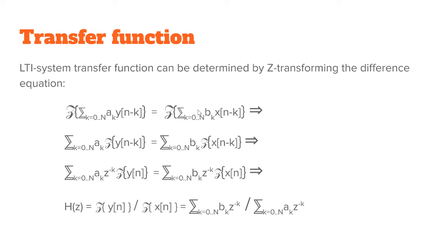So the transfer function for any linear time invariant digital system has exactly the same coefficients as the difference equation. Nice. That makes life much easier.